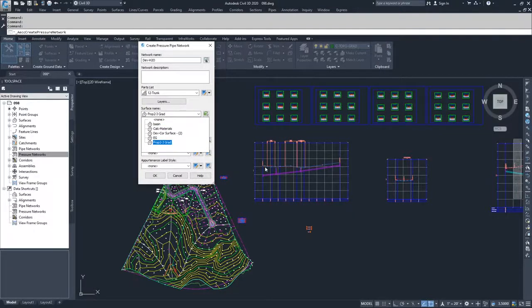And so I know from our development profile that our EG surface, for the most part, is always underneath our development profile. So I can use the EG surface to dictate the depths on my pipe. There's a small portion in here where it's slightly above the development profile. And so if I wanted to, I could set my design depth a little lower to account for that issue right in there, and then I would have more than enough cover.